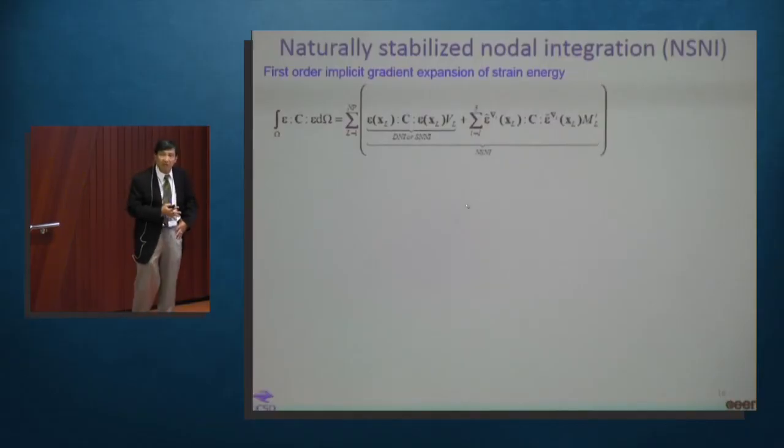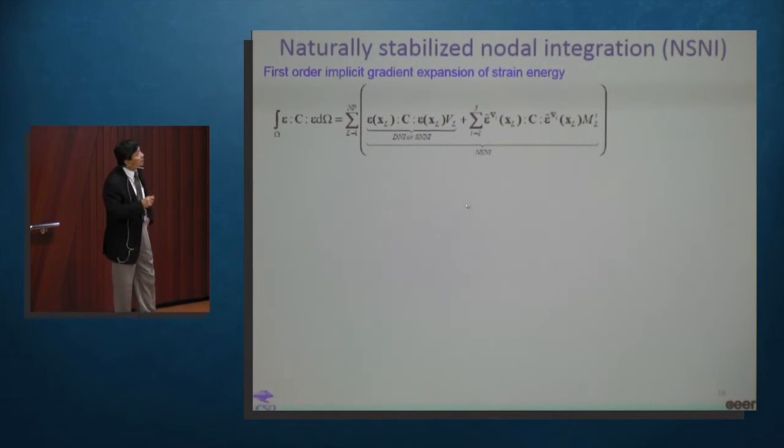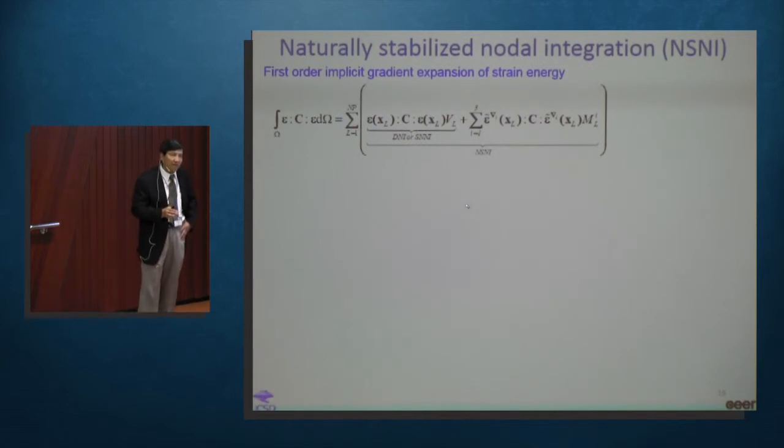Okay, so the last thing is to recover from this rank instability. Well, we know nodal integration will have spurious singular modes. With smoothing of strain in SCNI or SNNI, it kills those spurious singular modes, but it still has some low energy modes that can be excited once you have a very high strain rate problem.